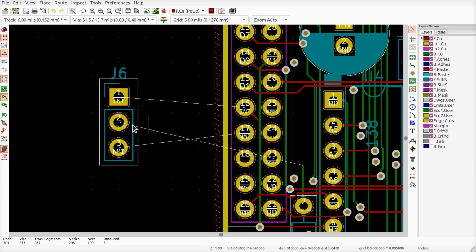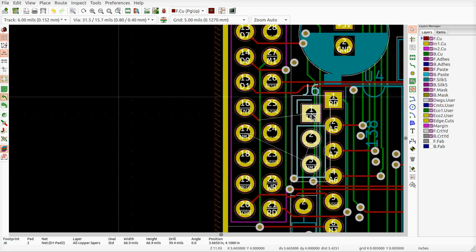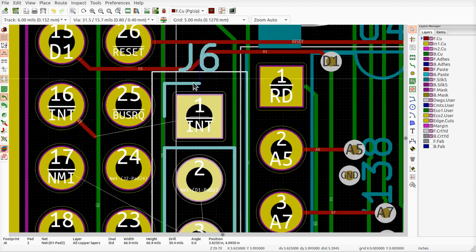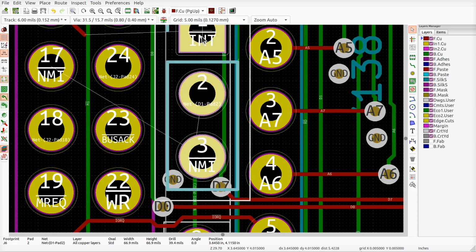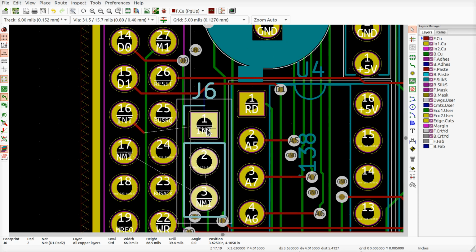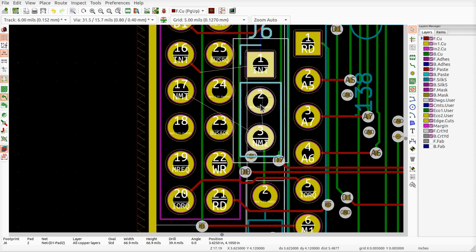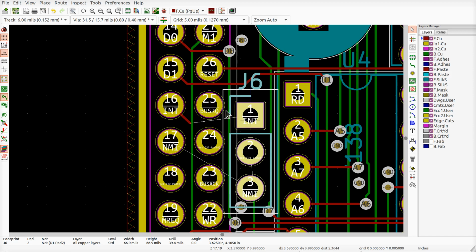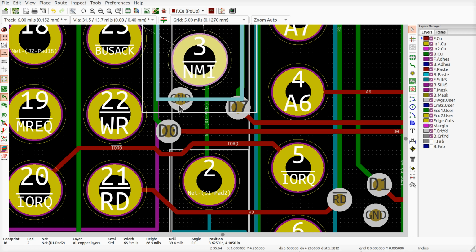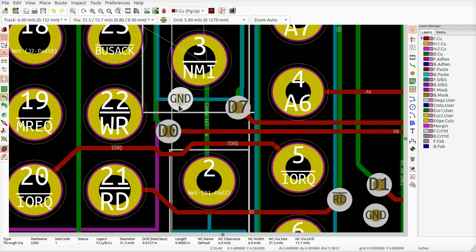Okay, moving along. Move this into here. Let's see if we can shoehorn that sucker in there. Now, of course, it's going to yell and scream about overlapping parts when we go to do the design rule checking. But we know it's going to fit. Now, I don't know how much I want to keep this aligned with the other pins here. Again, I don't want to think somebody might put a shunt across there, so staggering it might actually be a good idea. I'm going to take this ground via and get it out of my way.